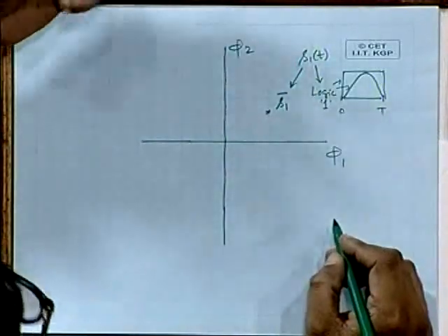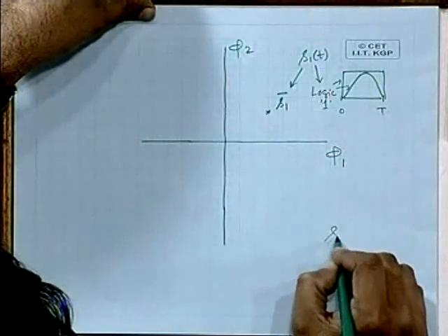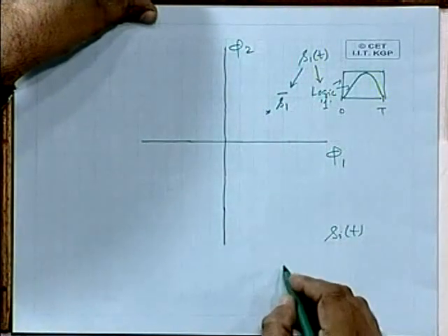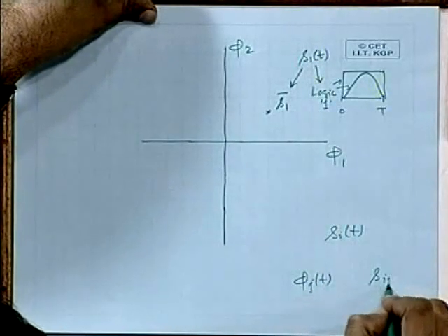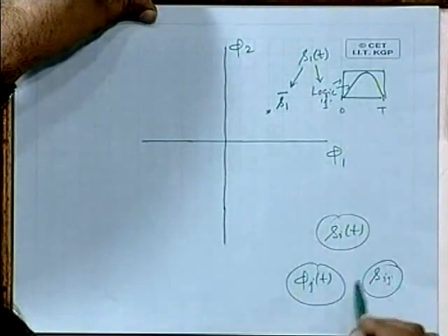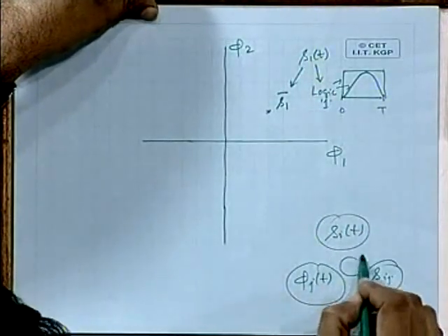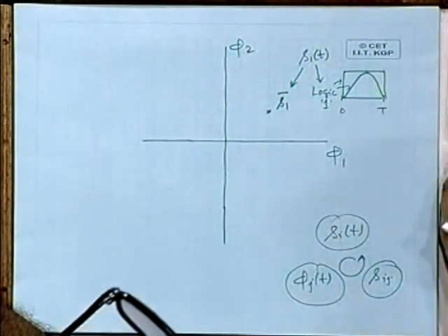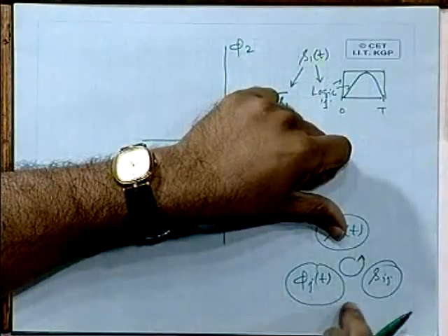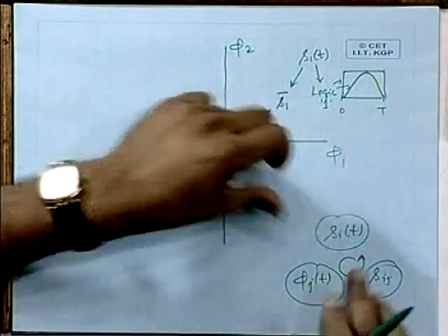See, in our Gram-Schmidt orthogonalization procedure, how did we start? We started with the Si(t)s, then brought in the concept of phi j's. In the process, they are related through some Sij's. How are they related? They are related in the sense that if I know two of them, I know the third one uniquely. If I know only one of them, or if I decide for some other reason like bandwidth that I decide about one of them, then again I have a freedom between the other two.